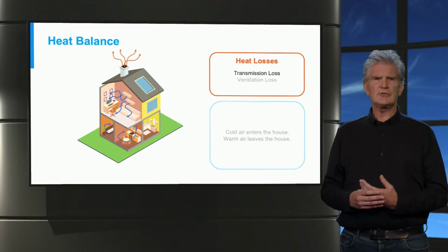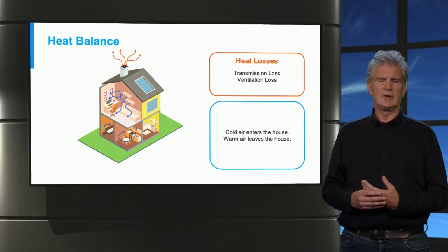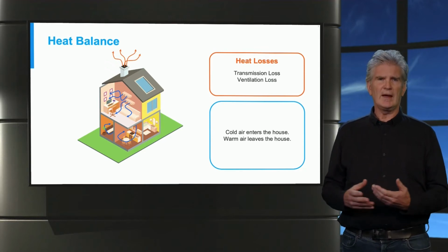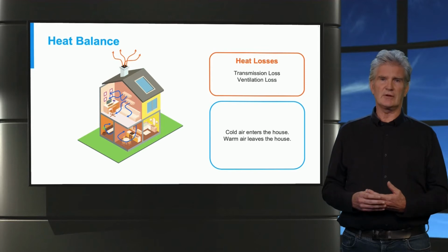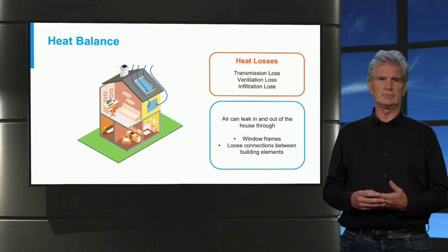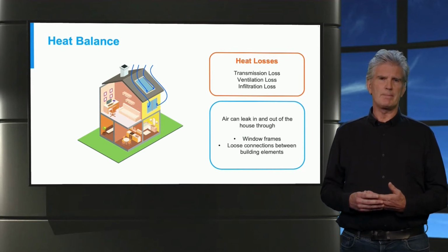At the same time, there's also a heat loss caused by ventilation. Cold air enters the house, and when there is no heat recovery, warm air leaves the house, and as a consequence, there is a heat loss. Additionally, there is a heat loss caused by infiltration. That is the unwanted leakage of air through the building envelope.